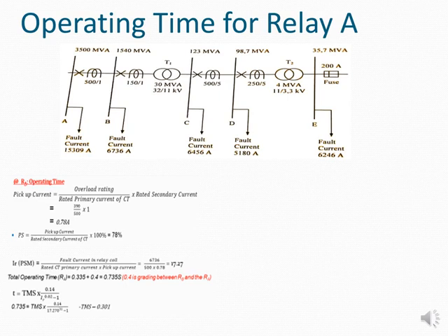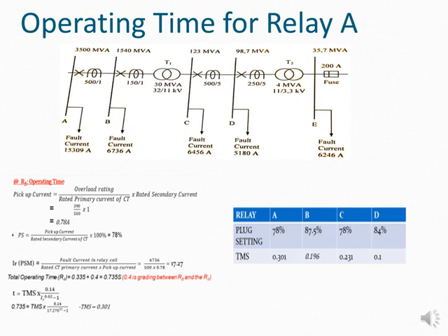I then utilize that to work out what my TMS is going to be. And that would be the end because I don't have to do my remote side if I don't have another CT that is going to be further uphill.